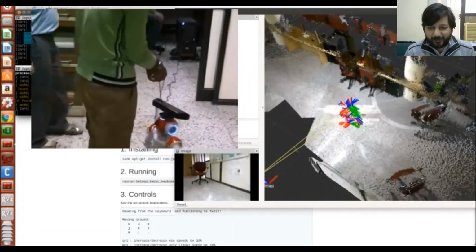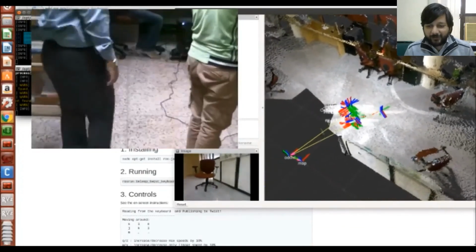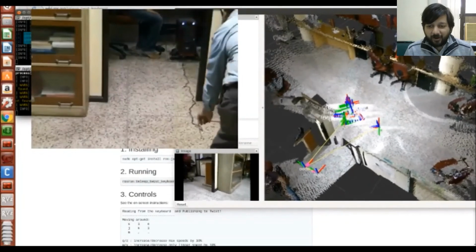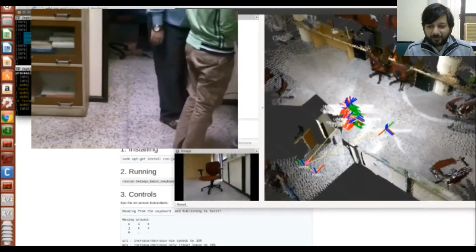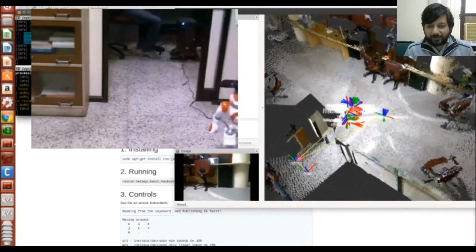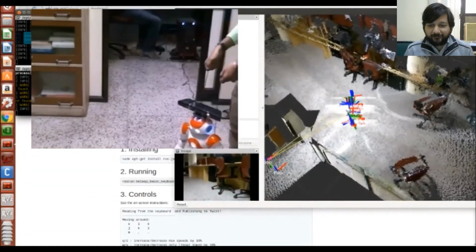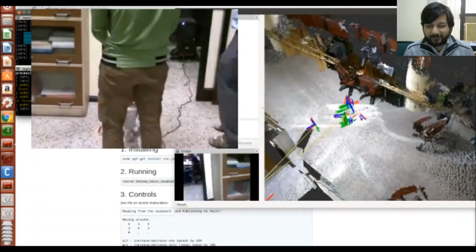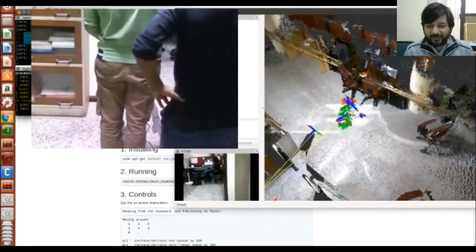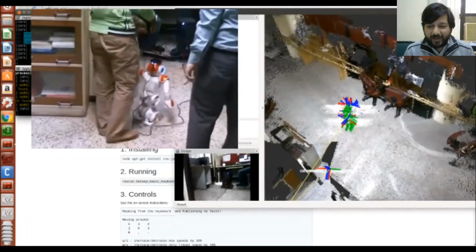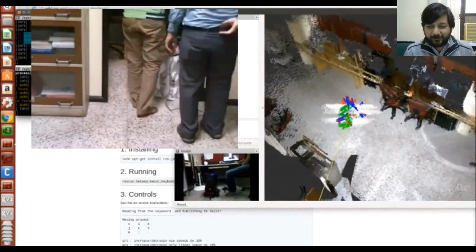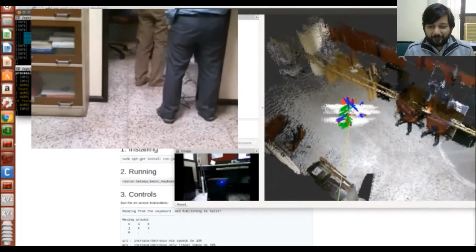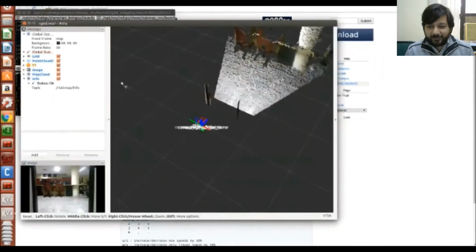And just for visual display, on the right is where you see the dense map, which is all the RGBD, which is all the points that it sees projected on an empty canvas. It's looking at how the different corners of different computer systems and bookshelves are moving. And of course, those are stationary, so it calculates its own position based on how these features appear to be moving in its own image.